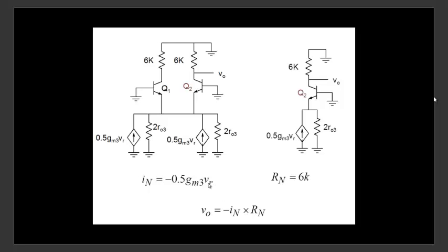Final output voltage, we know gm3 VR, and you can calculate how much of it appears at this particular point. So as I said, building a Norton's equivalent helps to simplify a lot of places. Wherever you are interested in finding the voltage, build a Norton's equivalent. How much is the Norton's current here? Then see the path of the current. This is the current here.